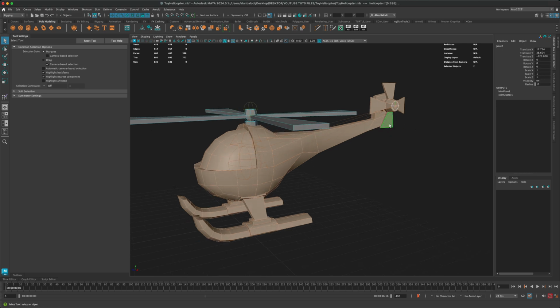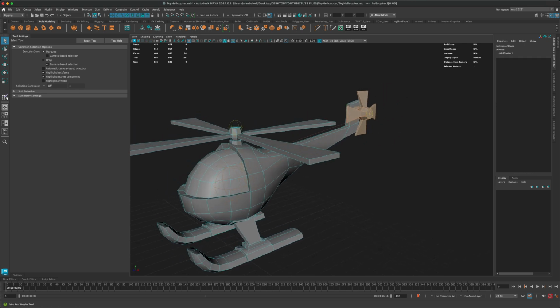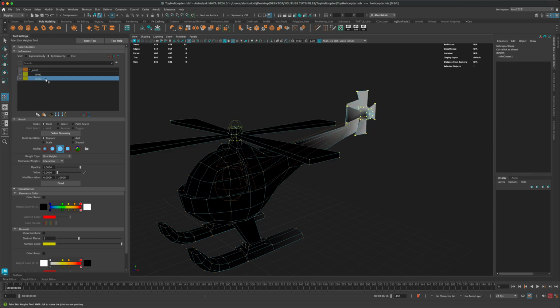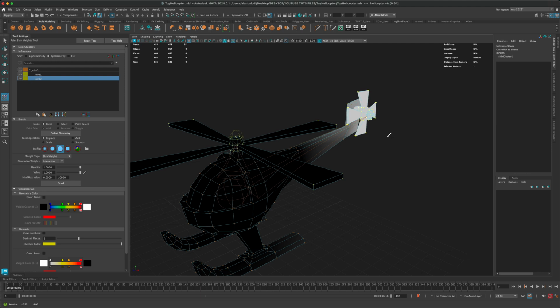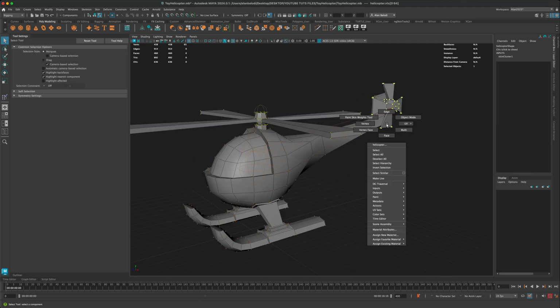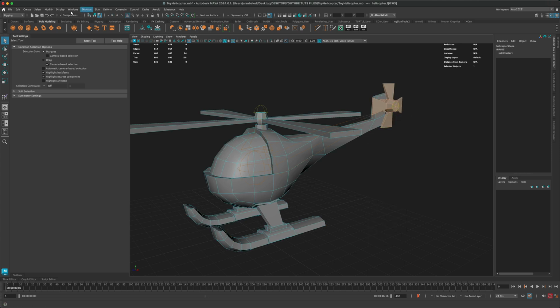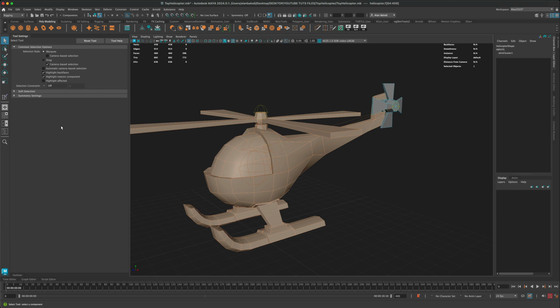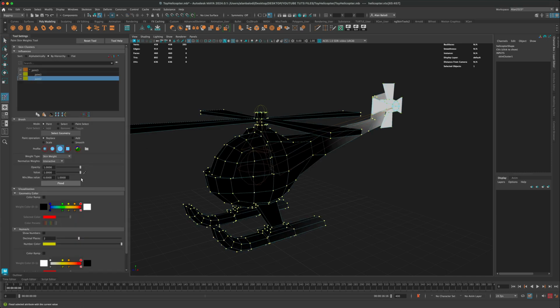I'm gonna go to faces actually and select this blade here, go back to paint. I know that this guy here, I should have named it, I didn't, but it's called joint 2. I'm gonna do the same thing. I'm gonna flood this 100%, right? Assign all the verts to this joint 100%. And I'm going to repeat the process of reversing. So inverse, go back to paint weights and dial this back down to 0 and flood this.